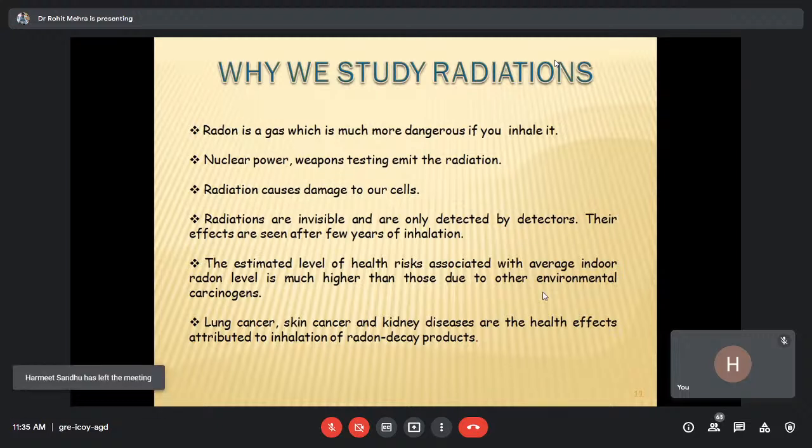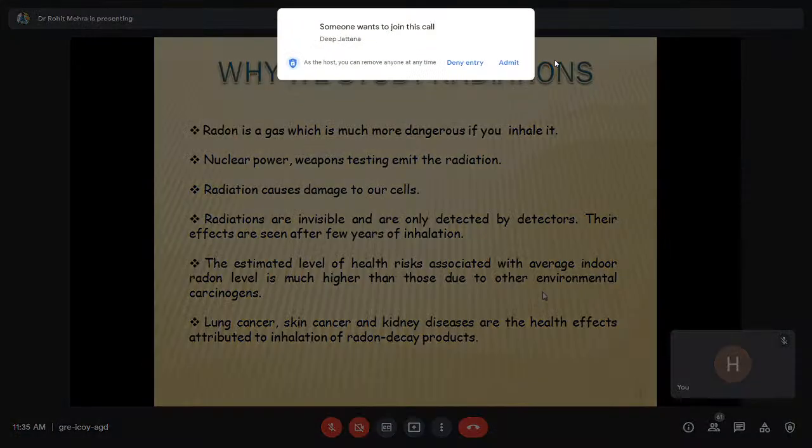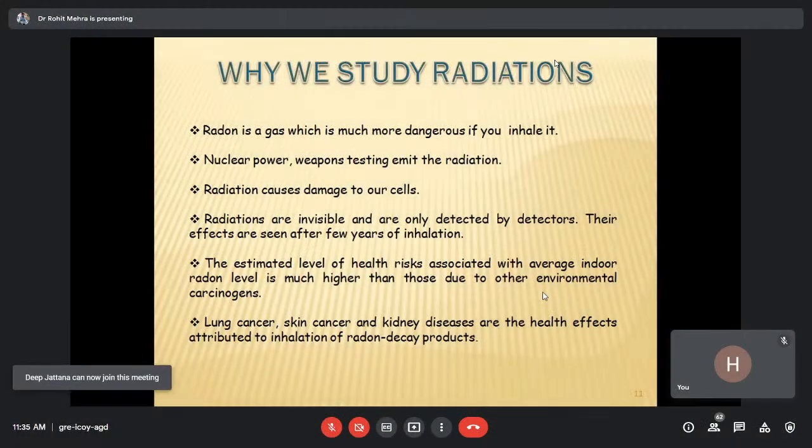Like even our kitchens have very little ventilation. We have closed kitchens. We use only the chimney, don't prefer to have a window in the kitchen, and we rather don't open those windows. So we make a glass partition, but where the ventilation is poor, there the chances are higher that you could have more trapping of the radiation emitted from the different building materials. So that is why it is important to have good ventilation conditions. Also, it is important to have a good choice of materials.